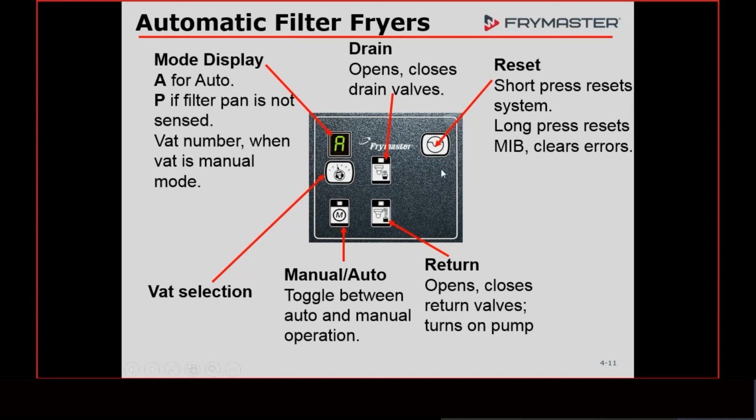One thing on this reset: when you come out of the manual mode, it puts everything in the closed position. So if you're changing an actuator, close the valve, hit the reset, and plug in the actuator that you're changing. Then when you install it on that closed valve, the actuator knows that it's closed because it was in the closed position when we hit this reset. As long as the valve is physically closed, it's going to start off closed. Then when you go to open it, it knows to open.